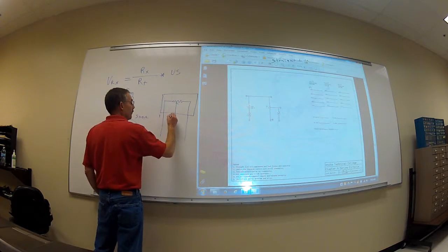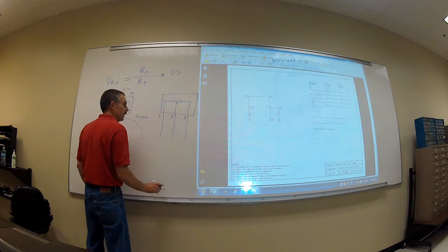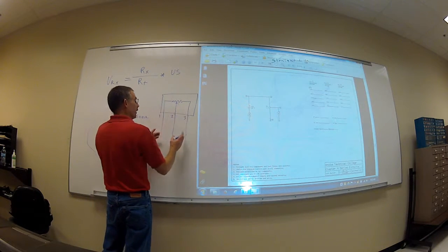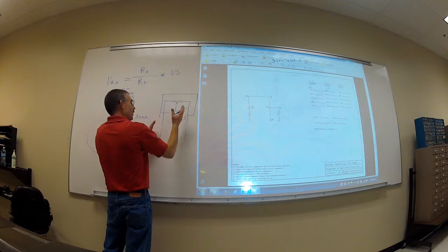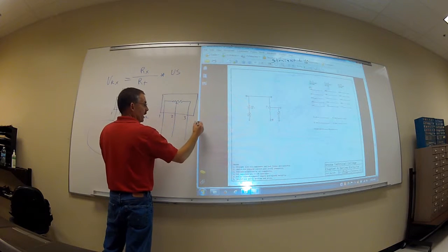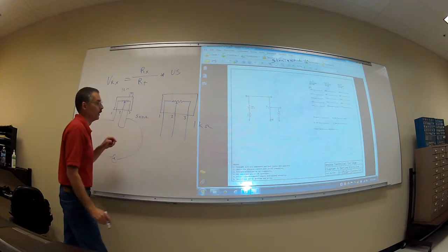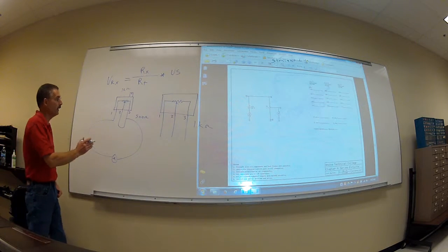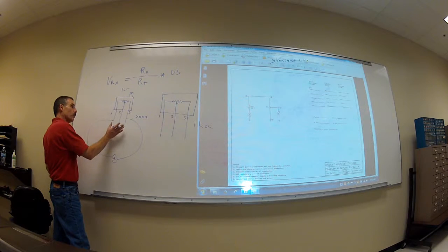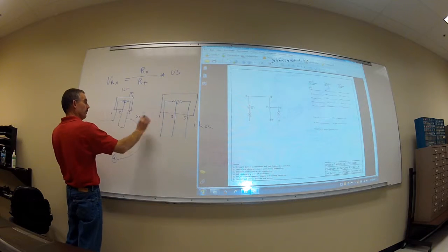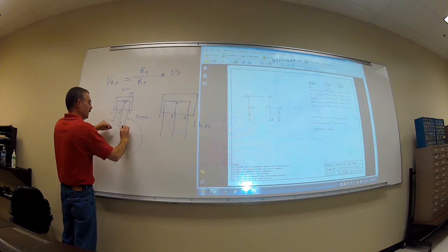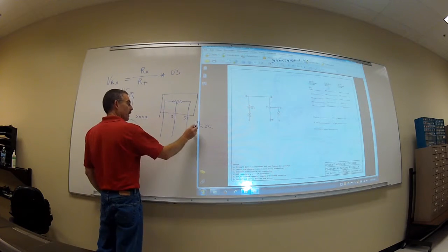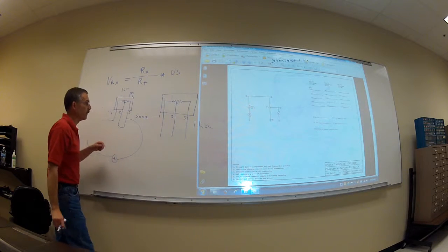Then if I did the same thing here and I pull it out of my circuit and I leave my jumper in my circuit, I don't have this jumper in here. What's going to happen is that I'm not going to be shorting out this half of that resistance. So now I measure across pins 1 and 3, and I'm going to measure 1 kilo ohm. So the easiest way is to leave that potentiometer in there, remove any of the power or anything that's going to it, bring in your ohm meter on your breadboard and measure it. So you get your 500 ohms, so you're not measuring this 1 kilo ohm when it comes out.